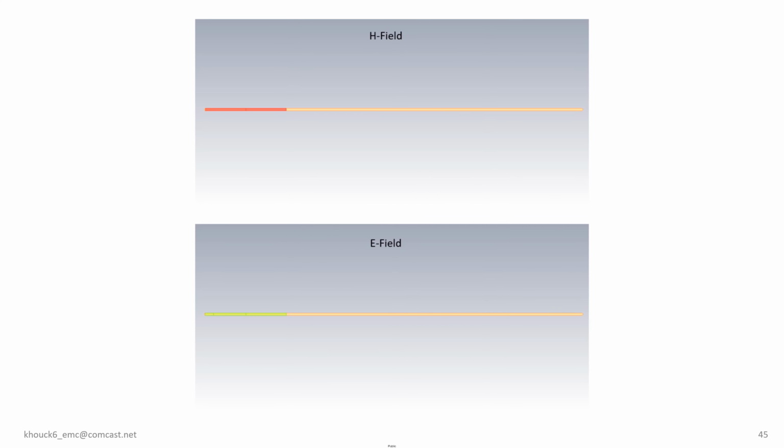In a transmission line where the impedance is lower than the termination resistor, field energy propagates from the source towards the termination resistor. Upon reaching the termination resistor, the energy undergoes a transformation into heat. As a result, the termination resistor develops a voltage higher than that of the incoming wave, while the current through the resistor is lower than that of the transmission line. Subsequently, the stronger electric field and weaker magnetic field propagate back towards the source, representing a fixed energy reflection.